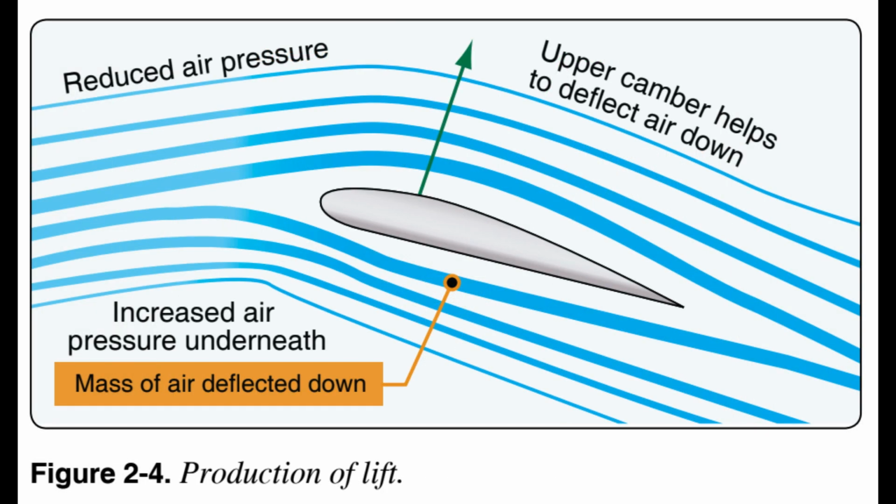Lift is generated when an object changes the direction of flow of a fluid or when the fluid is forced to move by the object passing through it. When the object and fluid move relative to each other and the object turns the fluid flow in a direction perpendicular to that flow, the force required to do this work creates an equal and opposite force that is lift. The object may be moving through a stationary fluid, or the fluid may be flowing past a stationary object. These two are effectively identical as, in principle, it is only the frame of reference of the viewer which differs.